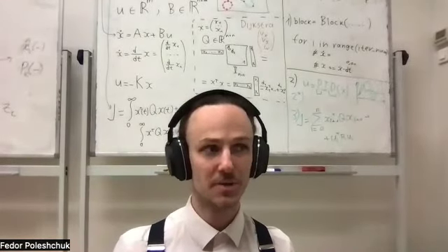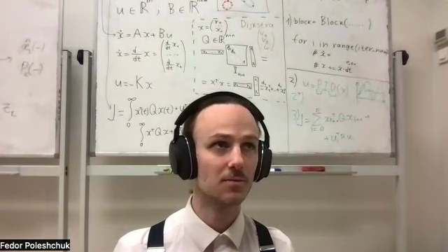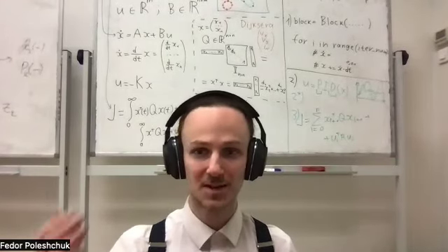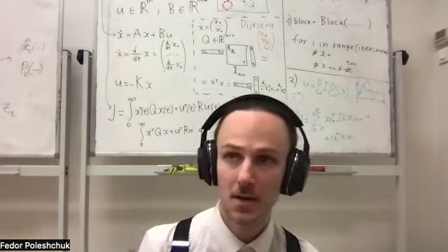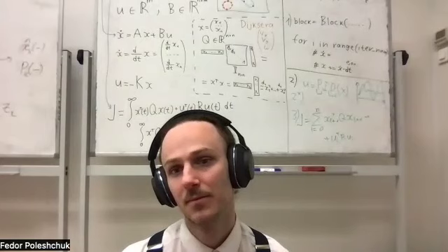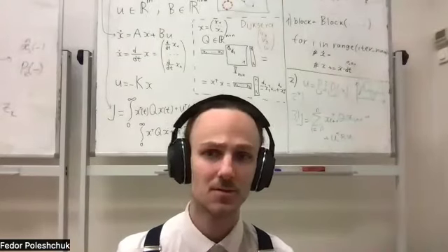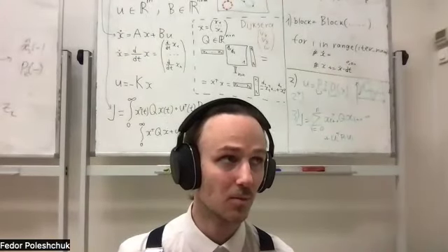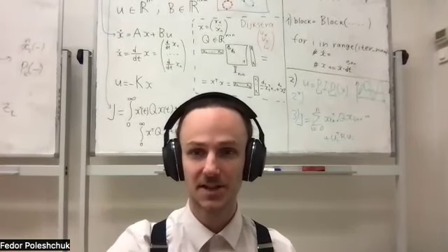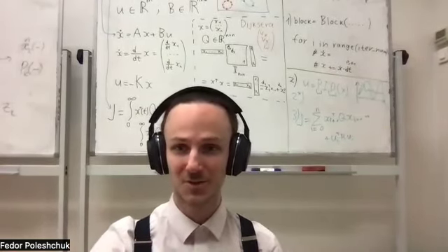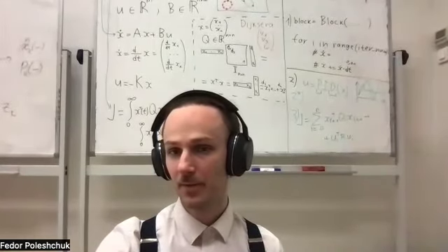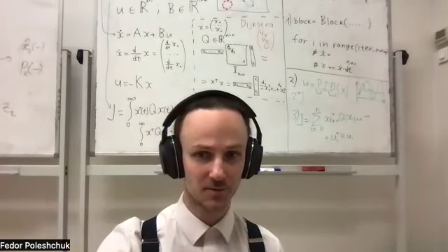And tuning PID is tedious and time consuming. It consumes your time as a control engineer. If we don't have models, we will have to use PID, that's for sure. Like servos, they just have to hold the position no matter what. We don't know exactly the torques that will have to be applied.